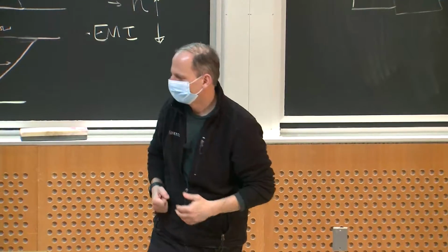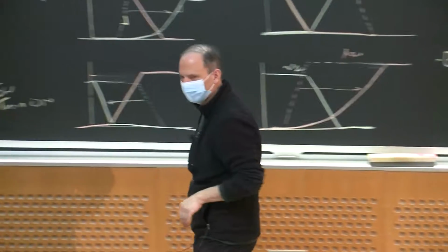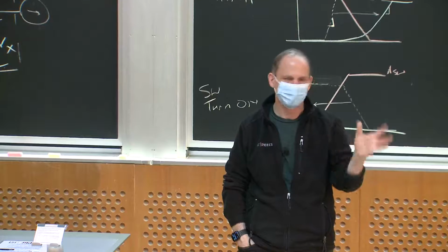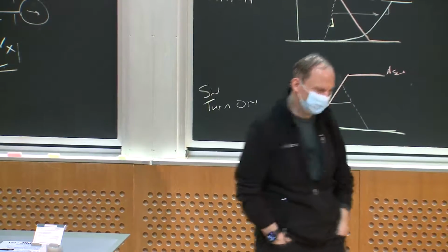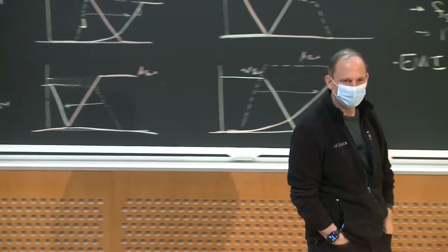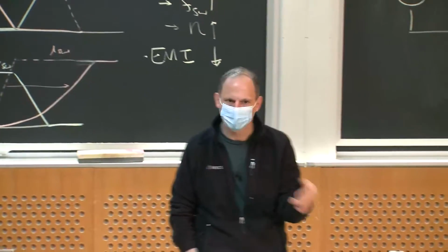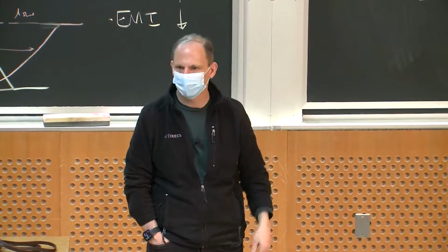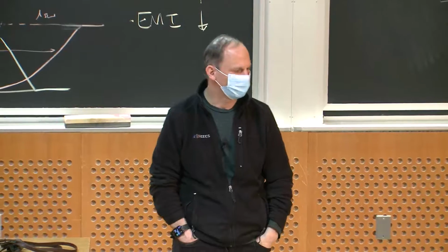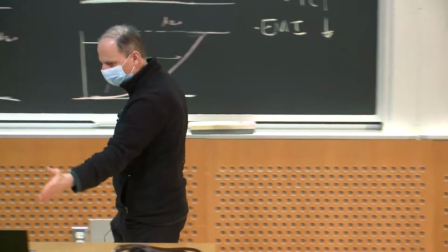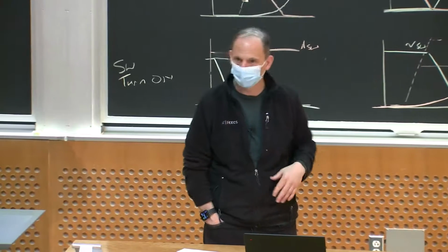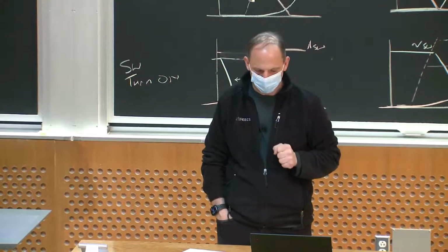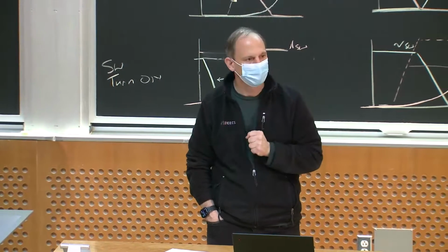And so this is a complicated circuit, relatively speaking, especially when he did this in the late 80s, early 90s, as controls and sensing and everything was really complicated. On the other hand, at high powers, you don't really mind, right? Compared to the previous inverter I showed you, the control for that has a lot of stuff, but it's pretty simple. You just got to sense current and make your switching decisions based on commanded currents. This is much more complicated, but on the other hand, it lets you PWM any way you want. And they were running motors with this, and they were running all kinds of special motor controls. So this is a really good circuit for this kind of application.